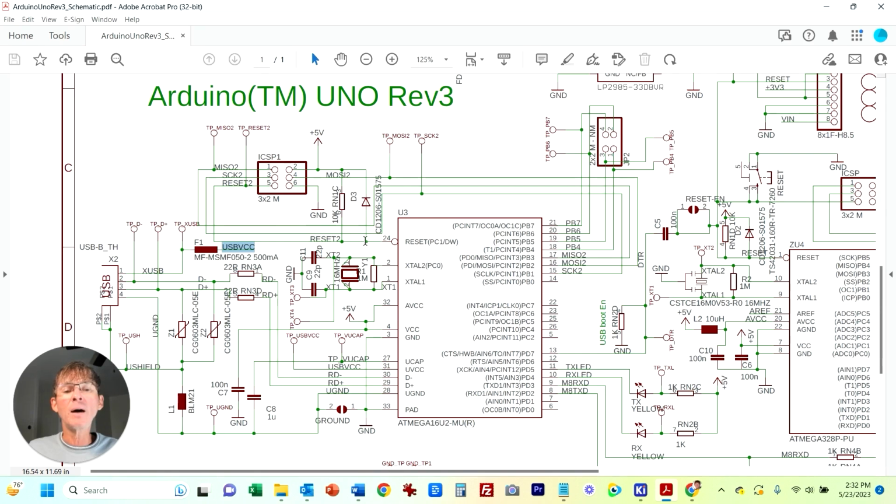We've got what looks like a reset line, and they've got this diode here. You can see it goes from the reset line up to the VCC line. Normally, the only time this would ever forward bias, so this side has to be higher, is if the reset line was higher than 5 volts. And that should not be the case.